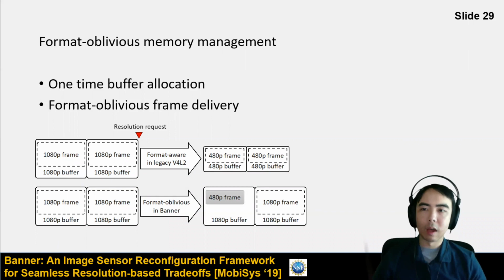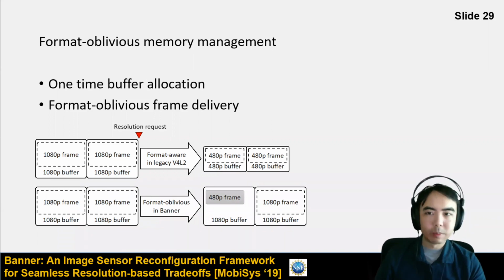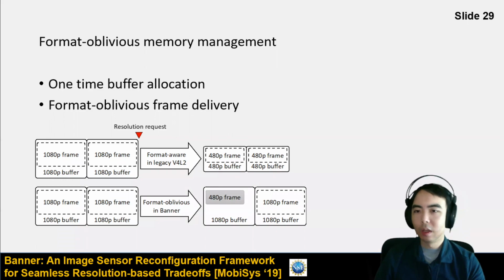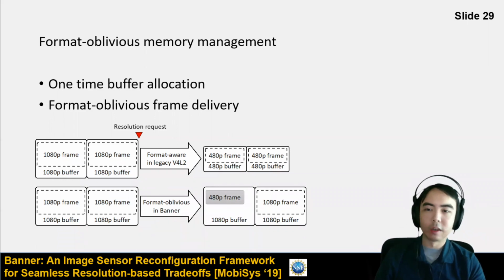You can leave a lot of it empty, and you'd be able to save on your memory transactions because you're operating with many fewer pixels as you're going through. So it's not like you're wasting memory throughput. You're wasting some memory allocation space, but you're not wasting the throughput, which is what really matters for power consumption. And then you're able to use that same space for 1080p frames, 480p frames, whatever p frames you want, as long as it's large enough to contain those frames. And then the media framework has a responsibility of communicating to the application where those memory segments are for each frame, but it can do the arithmetic just fine.